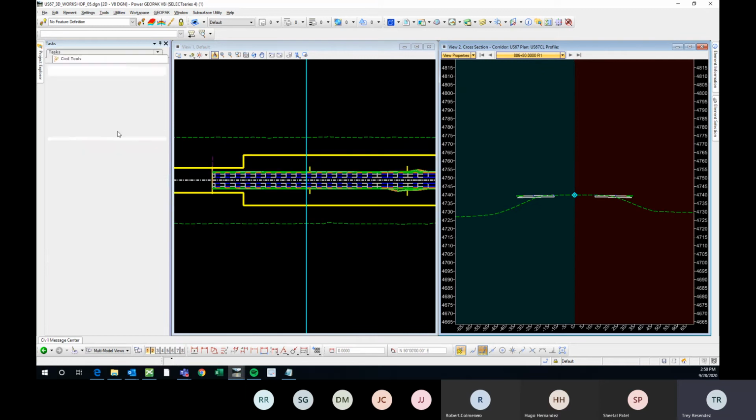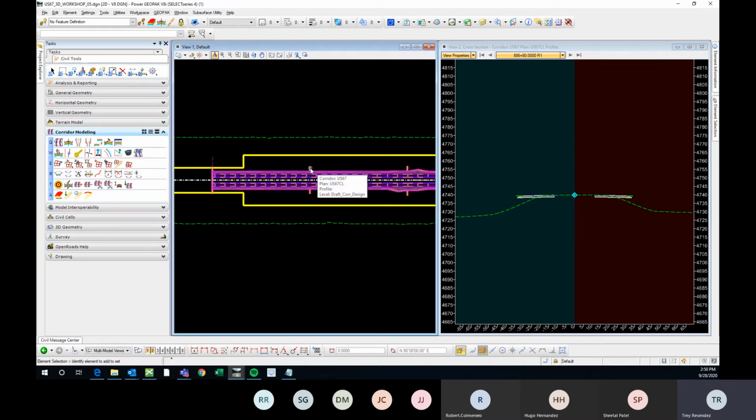What happens when you're using the point control by feature definition, the step that you cannot forget to do is to add the element that you're searching for as a corridor reference. So you can either come here to this fifth icon, add corridor reference, or you come over here. Then I'm going to locate this left right-of-way that we want to be controlled and not a template.